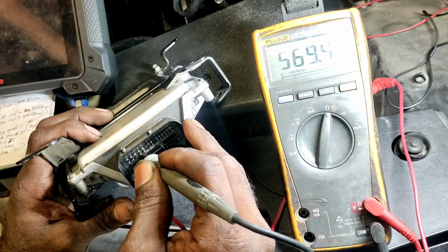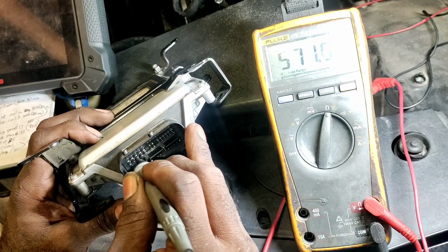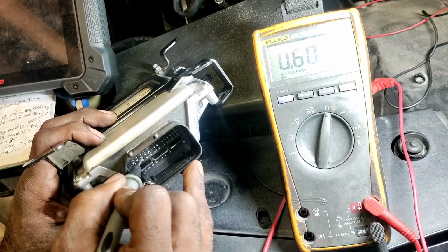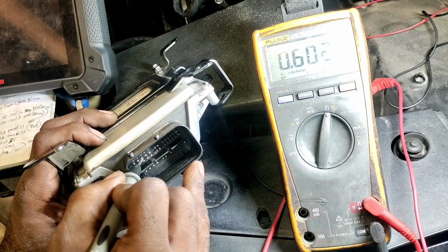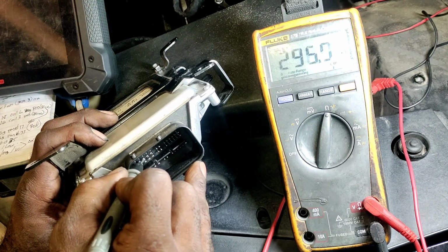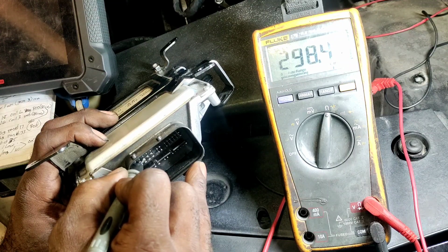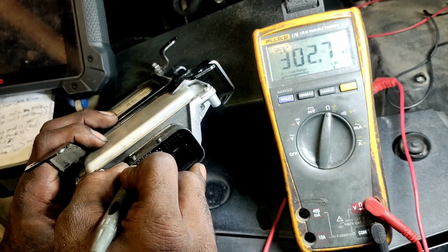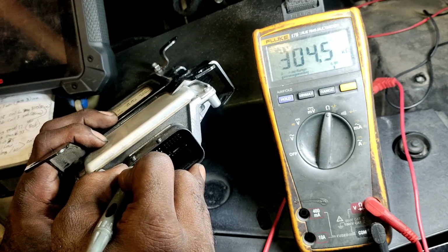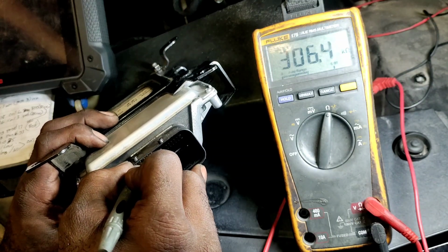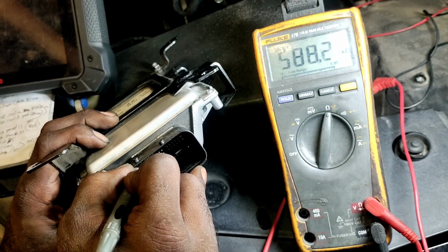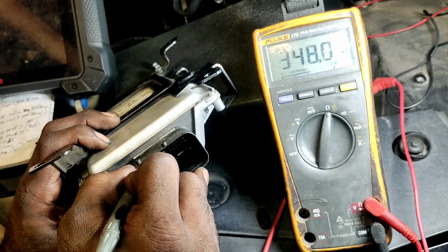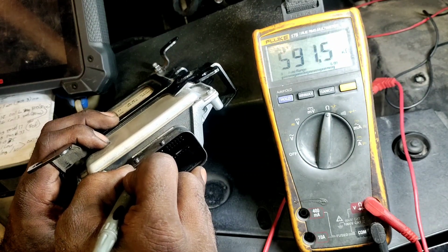Oh, fell off a little bit. Fell off again, hold on, bear with me. Let me get this right. Look at there. 297K ohms, and I'm not even bottomed out. Now I'm bottomed out, and it went to 303K ohms. I'm going to drag it back up to the top. I'm going slow, coming back up. And we hit that 5, and it's oscillating from 3 to 5 there. I'm in that sweet spot.